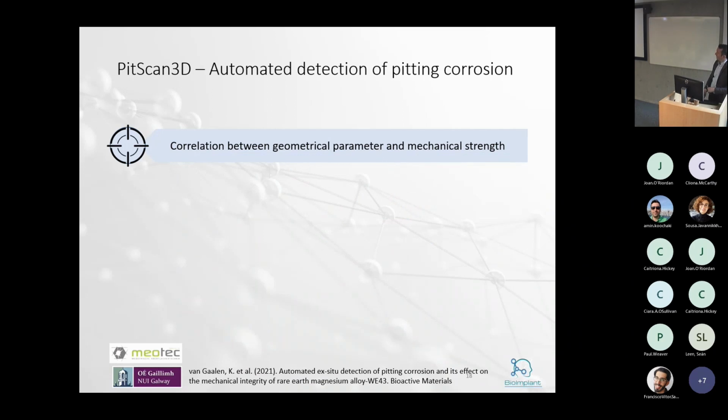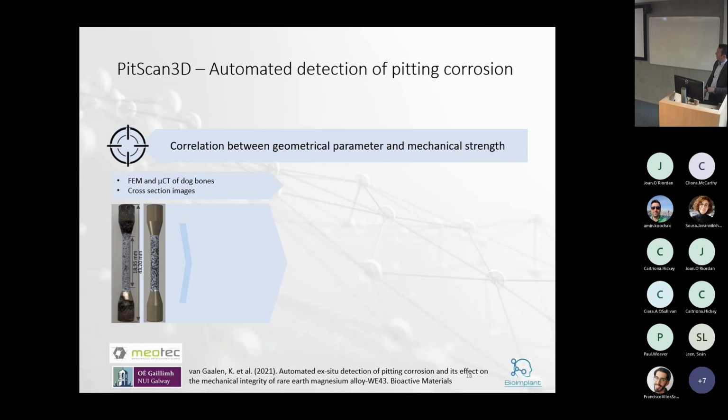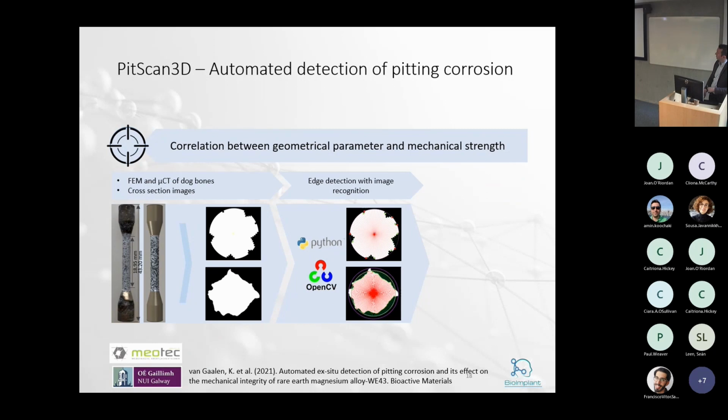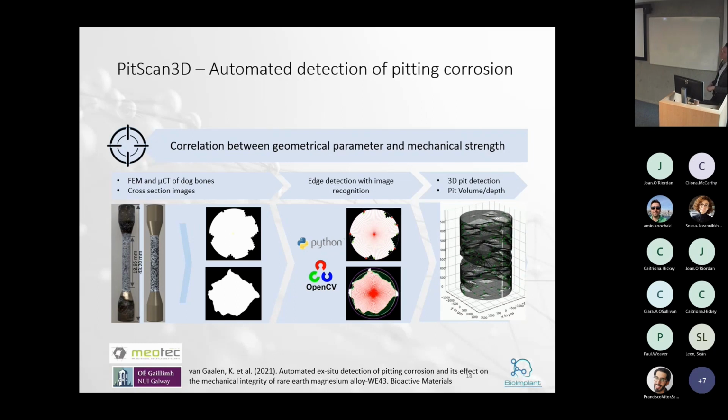To look at the corrosion of that surface, we had a micro CT based approach. We took these tensile specimens, we micro CT'd them in a micro CT scanner, and we essentially created a binarized image of these samples. And from that, we developed an automated framework that could measure the surface features and fully recreate your 3D geometric section of that.